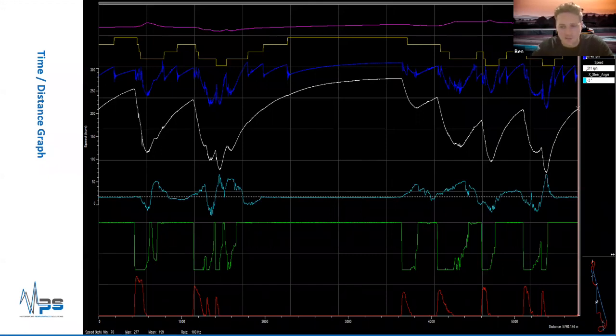So if you want to analyze yourself to yourself, or analyze yourself against another driver in your car, etc., you've got a constant in your data, which is turn 1, give or take, always occurs at the same point. So if one driver is braking too early in comparison to the other, or one's too late to turn in, etc., you have this distance measurement that you can reference on track.